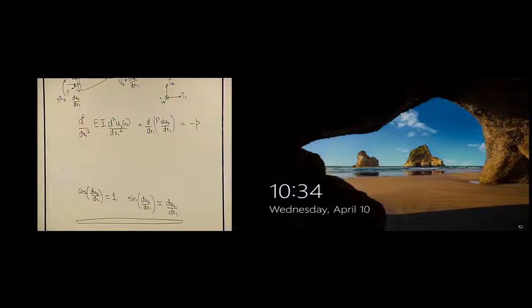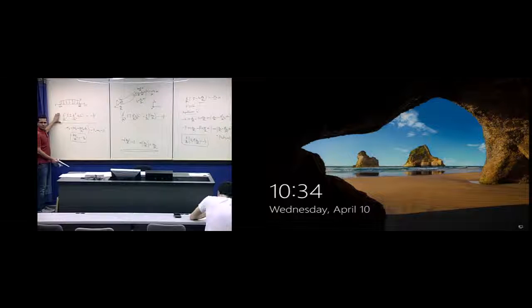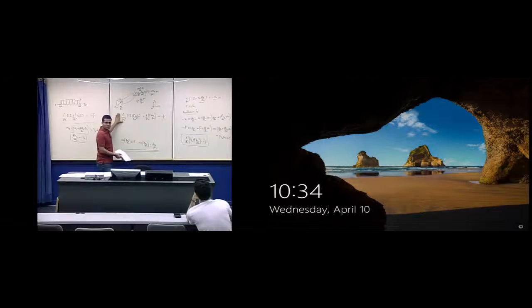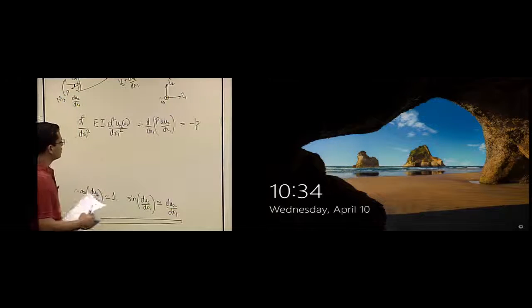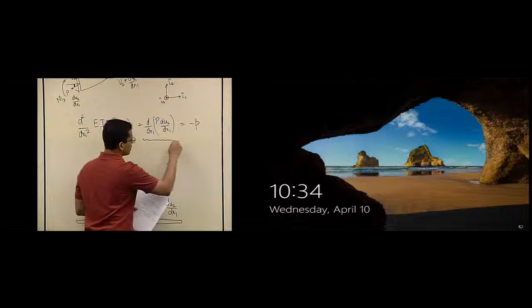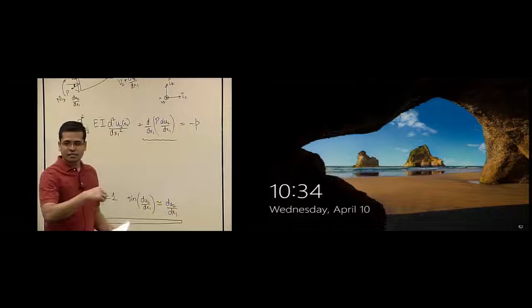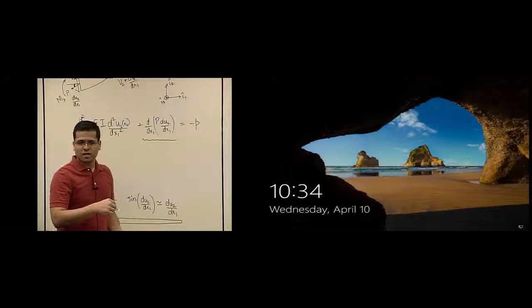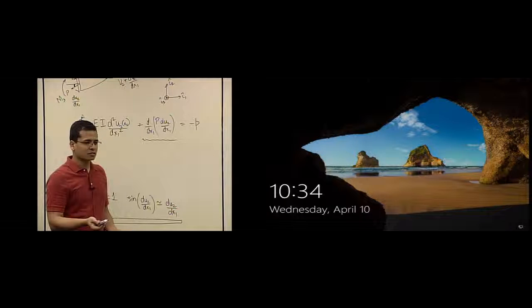So now let's compare the two equations. We had this governing differential equation before, where we did not have any axial compressive load or a coupling between the two, like bending and axial. And now we have an equation where we have contribution of axial load, right? So you see a term which directly enters the equilibrium equation as opposed to boundary conditions, right?